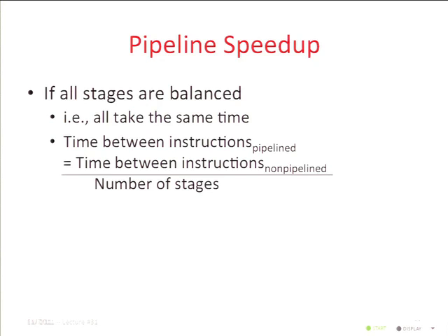So this is sort of the best case, and with the registers it's probably not even the attainable best case. Wouldn't it just be one clock-to-Q delay, since it's all the same registers? Each stage has to read from the register that's its input and write to the register that's its output. So if it was 200 before and it takes 10 to do this other stuff, then now it's become 210. There may be some ways to overlap that, but it's going to introduce a little overhead for sure.